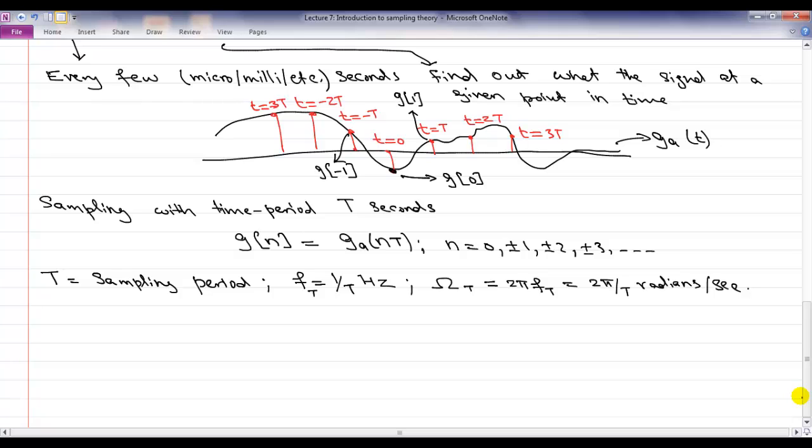What that is referring to is how the song was converted from the continuous world to discrete samples: by taking its samples at a rate of 44.1 kilohertz, which means you are taking 44,100 samples per second. Or every 1 over 44,100 seconds, you are taking a new sample. So pretty much every digital signal that you see, you will see associated with it a sampling rate, most often given in terms of hertz.